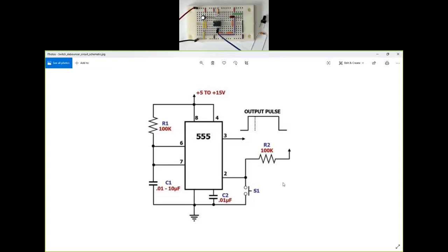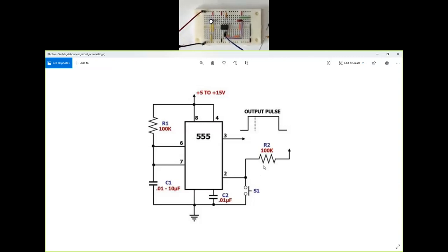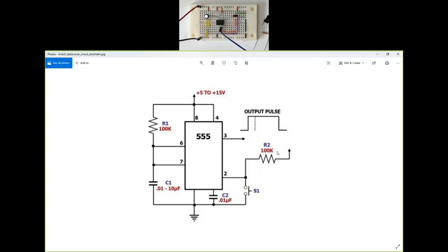And I can do that in PSpice, and I can do that in fake data without using the pull-up resistor. I only need to use the pull-up resistor when I actually operate the actual switch, which is shown to the right here. So that's my actual switch I'm going to debounce. So make a note of that: R2 only when a real switch is used, not the fake switch.